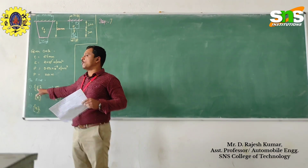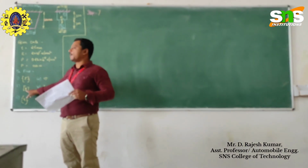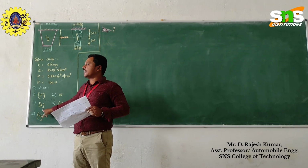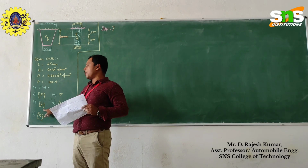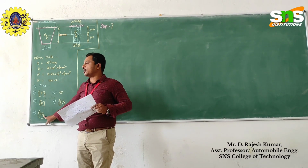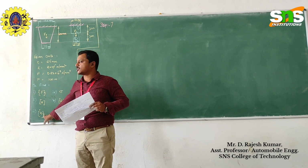We have found out the force vector by using the body force vector formula. Then by applying the boundary condition, we have found out K as well as U. K is the stiffness matrix: finding the elemental stiffness and then assembling it, we find the global stiffness matrix. Then by applying the boundary condition, we find the unknown displacement. U1 is 0 and U2, U3 you will be getting some value. So that is what we have seen so far in this problem.